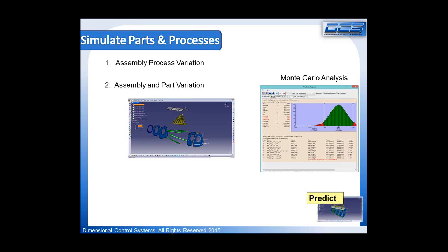Those are applied, and a Monte Carlo analysis is executed in order to be able to understand what the effects are. Again, thinking about the use of the finite element data to now take into account the impact of deformation that is caused through some sort of an effect that is going to cause the external skin of this aircraft to stretch or flex.